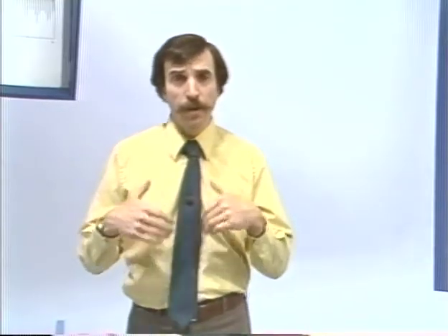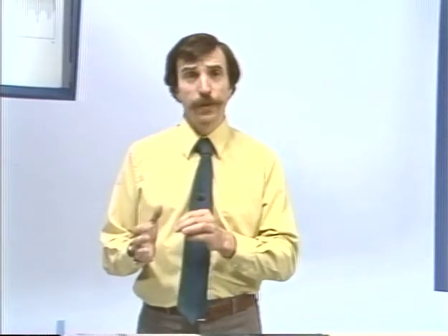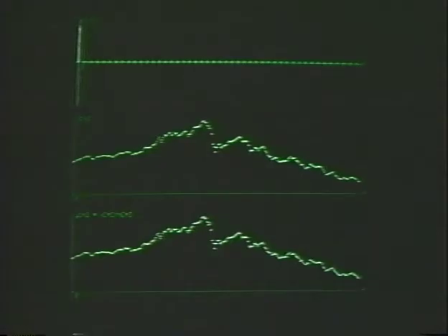So let's, in fact, go back to the Dow Jones average, and let me now show you what the result of filtering with a moving average filter would look like on the same Dow Jones Industrial Average sequence that I showed last time. So once again, we have the Dow Jones average from 1927 to roughly 1932. At the top, we see the impulse response for the moving average. Again, I remind you on an expanded time scale, and what's shown here is the moving average with just 1 point. So the output on the bottom trace is just simply identical to the input.